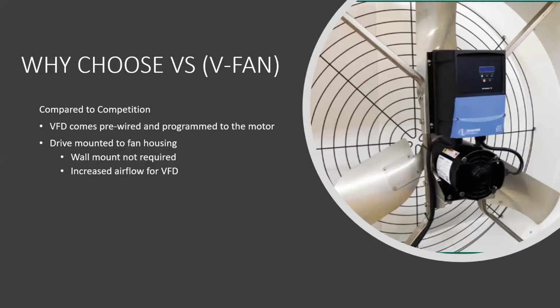And also, with it being mounted there on the fan, it's going to have increased airflow as the air exits the house through the fan. And so it's going to allow the VFD control to stay cooler.